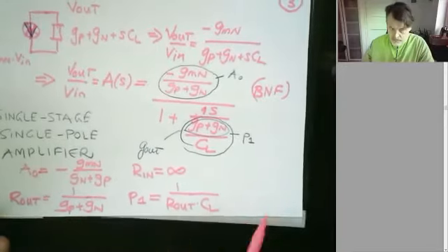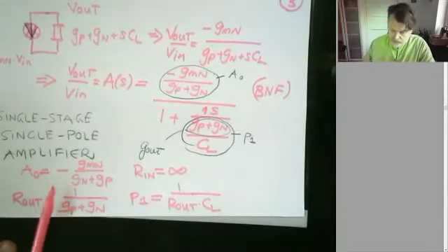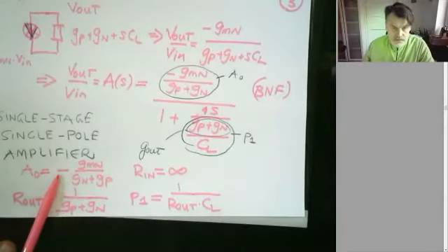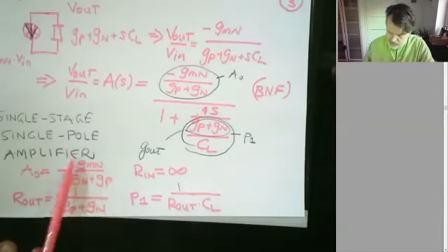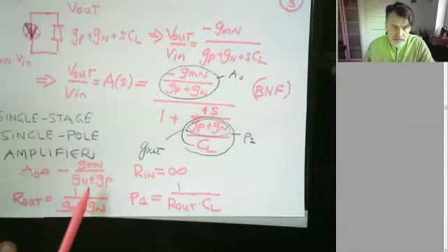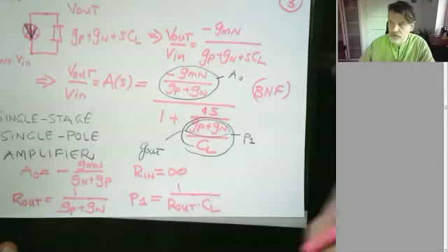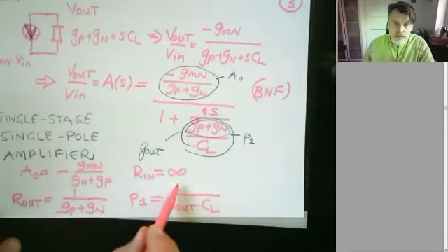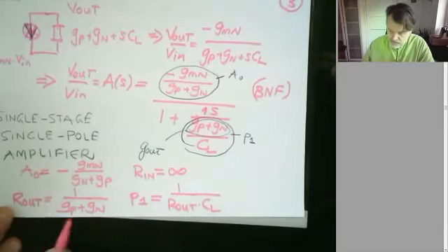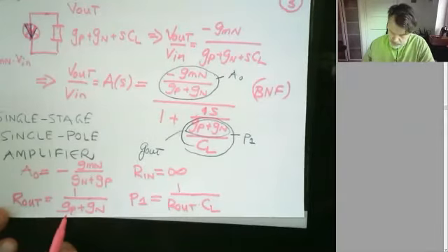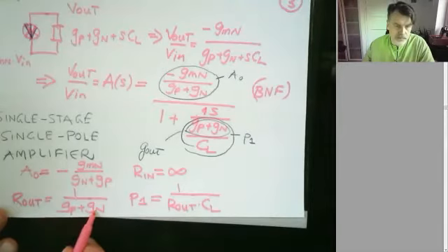All right, so for the common source stage, we have phase shift, 180 degrees. We have a high number. GM is a number which is much, much larger than GN plus GP. It has to be, otherwise the transistor wouldn't have any gain, so it wouldn't make sense to use it. Rin is infinite. The output impedance is pretty high. So GP and GN are small numbers.